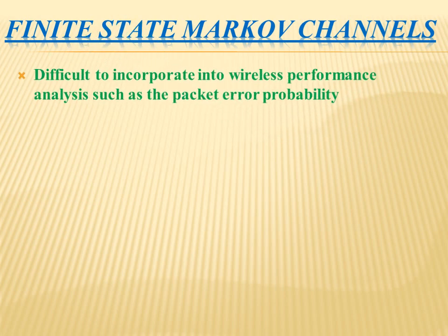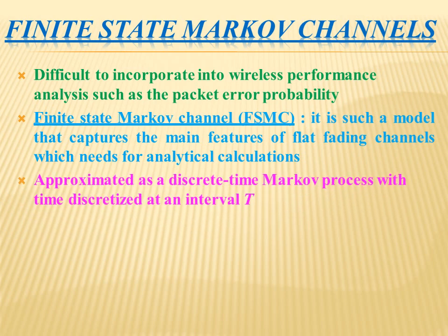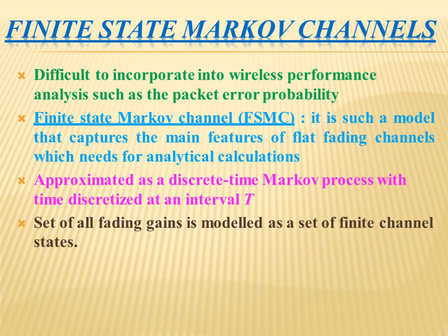Finite state Markov channel is a channel which is suitable for narrowband fading models. The complex mathematical characterization of flat fading can be difficult to incorporate into wireless performance analysis such as packet error probability. The finite state Markov channel is a model that captures the main features of flat fading channels needed for analytical calculation. It is approximated as a discrete Markov process with time discretized at an interval t.